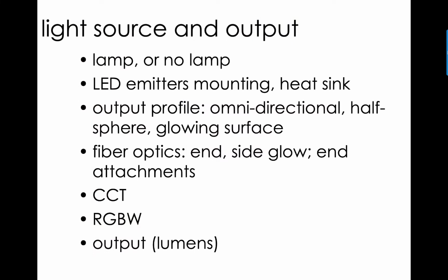So the other thing to consider is, are the lamps a lamp, or are they LED emitters that are just mounted on something? And if they are just mounted on something, remember that they are unidirectional, not omnidirectional, excuse me. So they only throw light in one direction, which means they'll be dark on one side. And that side is typically made of metal, so it reduces heat a bit, but also so that the LEDs can be affixed in a permanent and secure manner.